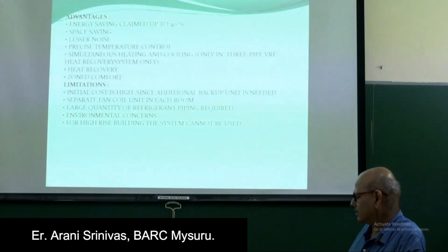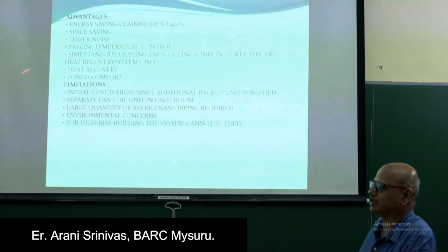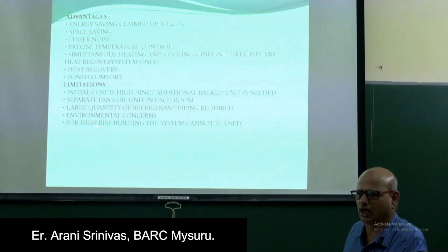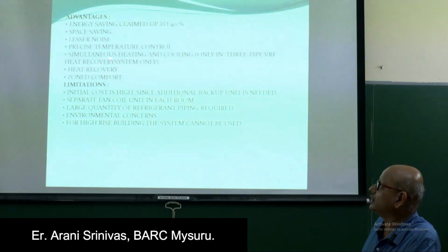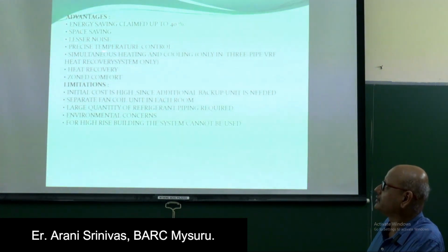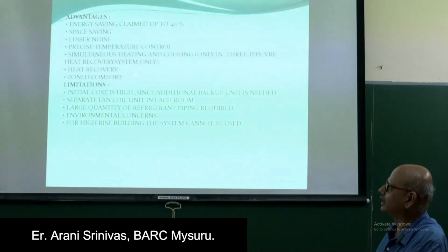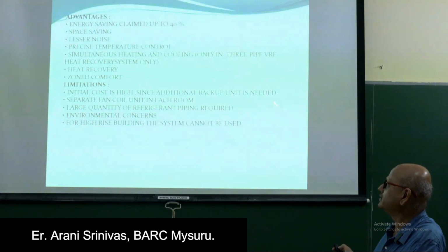See, the advantage of the VRF system is that it saves 40% energy, because controlled refrigerant flow is allowed, so your compressor will work at different RPM and you will have less power consumption. That is why energy saving claims up to 40%. Space saving, lesser noise, precise temperature control, simultaneous heating and cooling with only 3 pipes here. Heat recovery, zoned comfort.